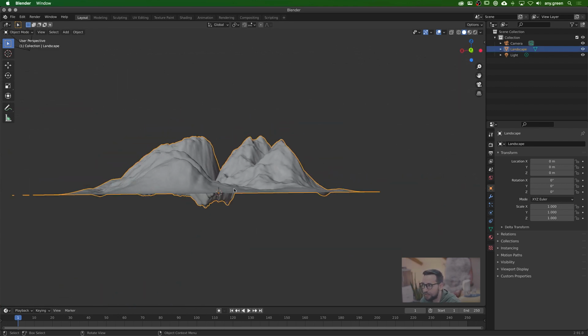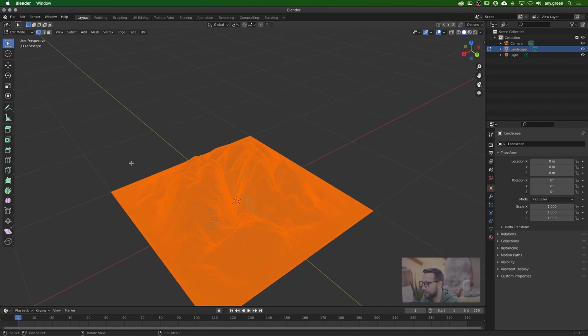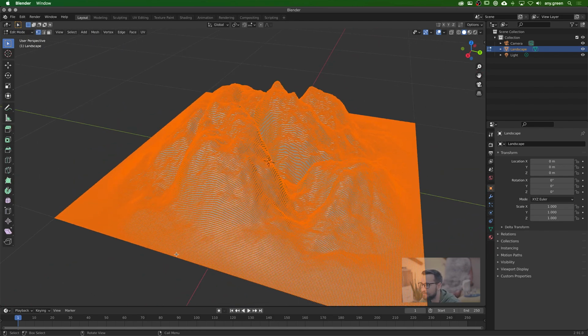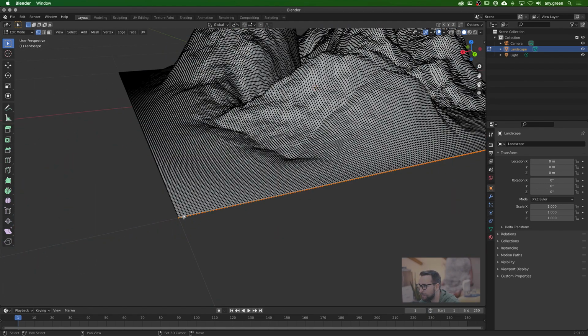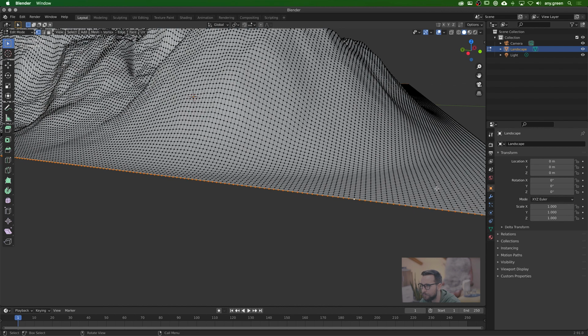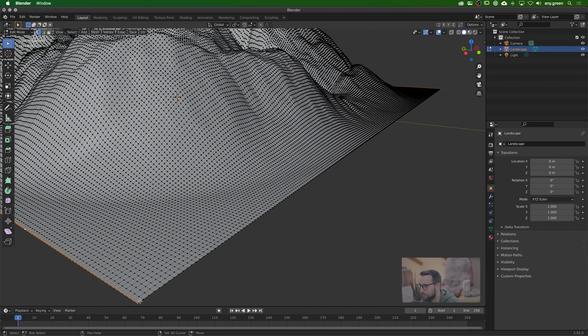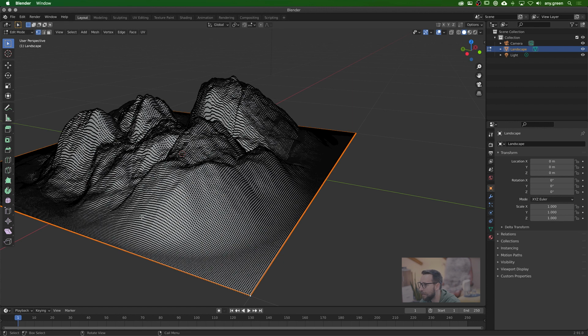All right, now we do need to give this a little bit of depth and volume, so it needs to be a closed shape. To do so, we can switch over to our edit mode here, and we can see it's already a pretty high resolution thing. Then we can double click on our edges here to select them. Didn't want that. There we go. And then we can just extrude it down. So what would be the smartest way of doing that? I hope I'm not breaking anything.